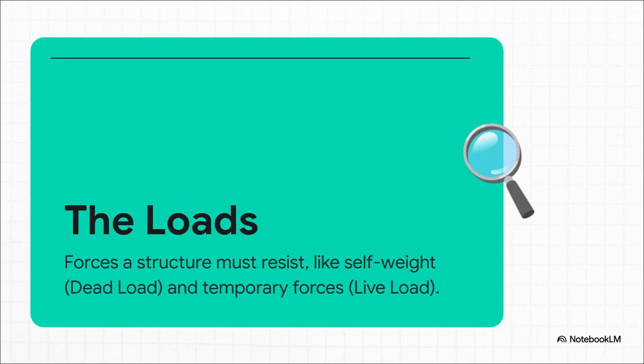The second element is loads. These are the forces that a structure has to fight against. This includes dead loads, which is the structure's own weight, and live loads, which are things like people or furniture. And, of course, you've also got environmental loads like wind or earthquakes.